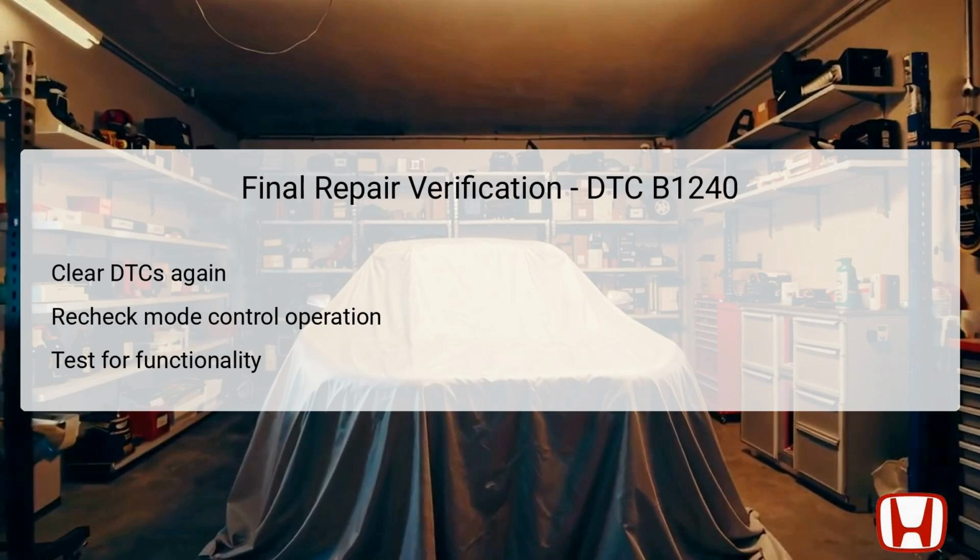It's also essential to perform a test drive or manual check of the climate control system to ensure all repairs have successfully mitigated the original issue. Monitoring any signs of error codes reappearing will help in assessing if the problem has been completely resolved. This step is fundamental for confirming the effectiveness of the repair made on the mode control motor circuit.